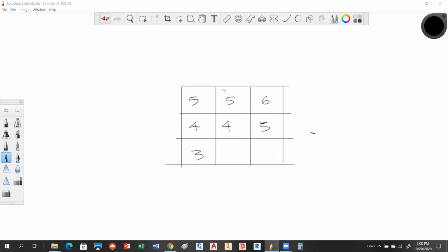Okay, so let me refill this. All right, so let's say I want to calculate the slope here. Let's say this represents feet of elevation. So we've got 5 feet, 5 feet, 10 feet. Let's say maybe this is 4 feet, maybe this is 8 feet, 7 feet, 1 foot, and 3 feet. So what we want to do is come up with an image that, instead of having elevation, tells us the slope in percent grade.